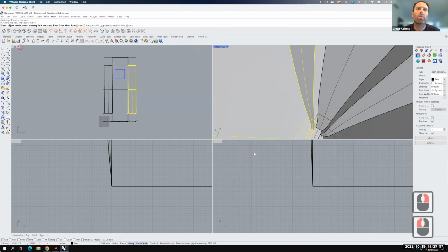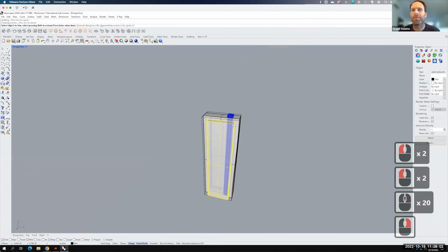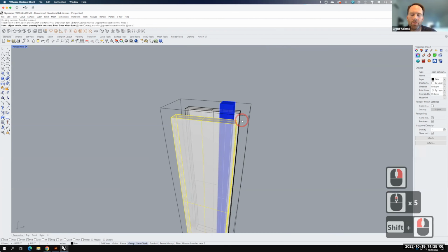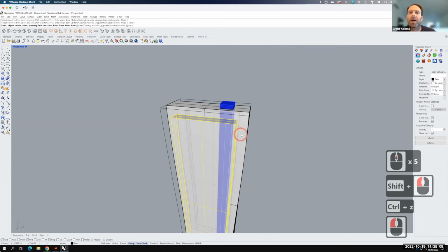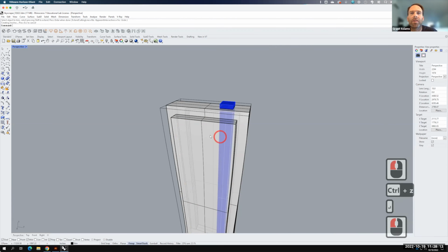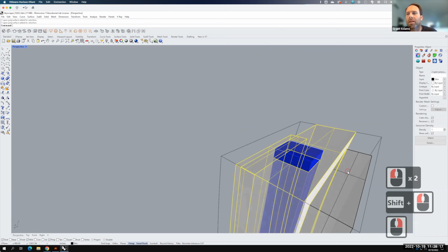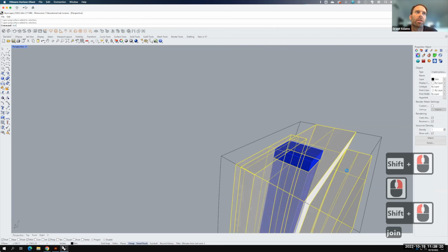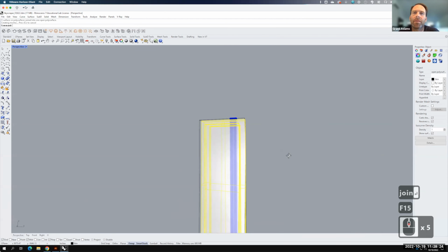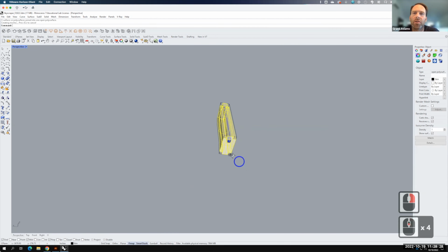That's much better when we go to unroll it from its surfaces. So let me step back here for a little bit. There it is. And now I could actually take this, oops, sorry, I still had trim active. I had to have another enter there. I could take these three pieces, 1, 2, and 3, and I could join all of those together, like that. So now they're all one kind of continuous surface.